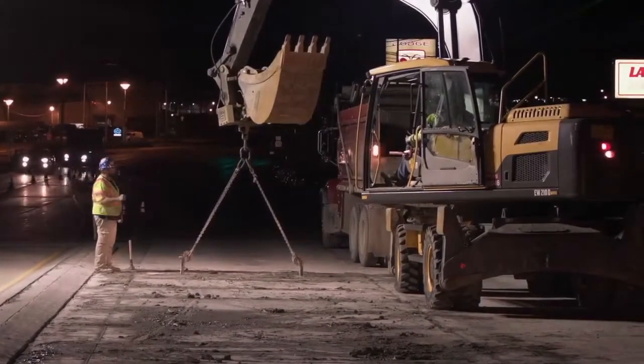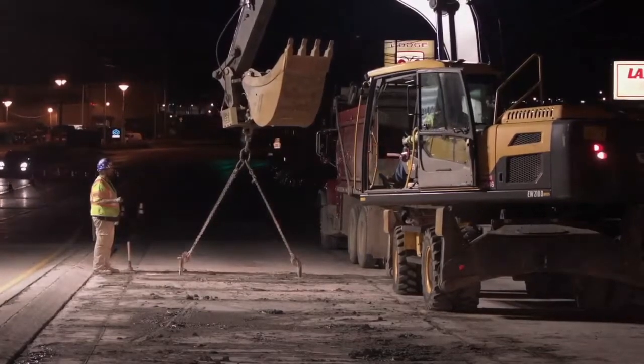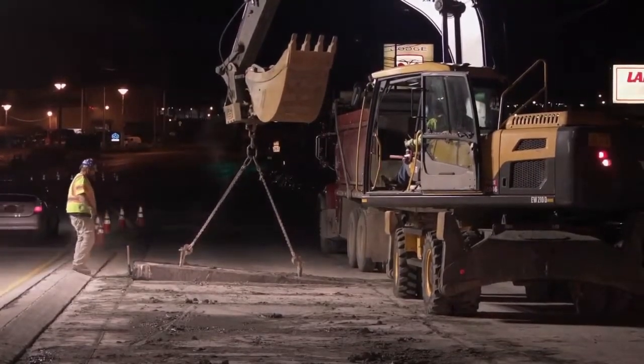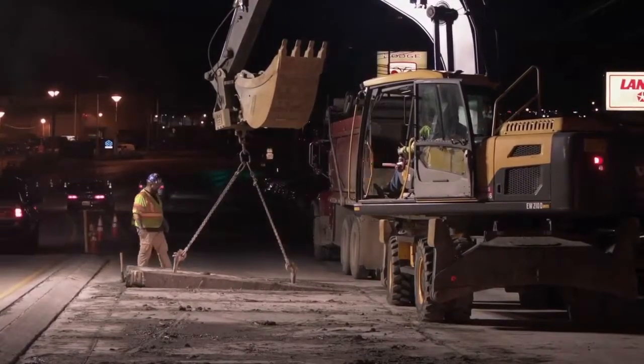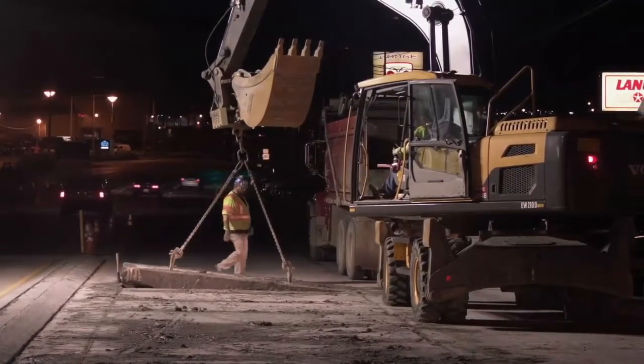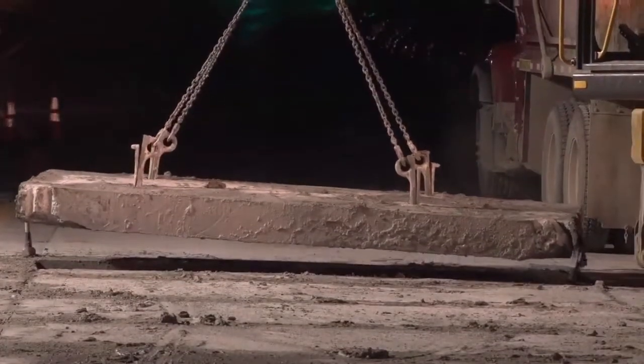If the adjacent pavement to remain in place is damaged during the pavement removal process by either breakback or spalling, the damaged area will be repaired at a minimum with a full-depth concrete pavement patch at no additional expense to the department.